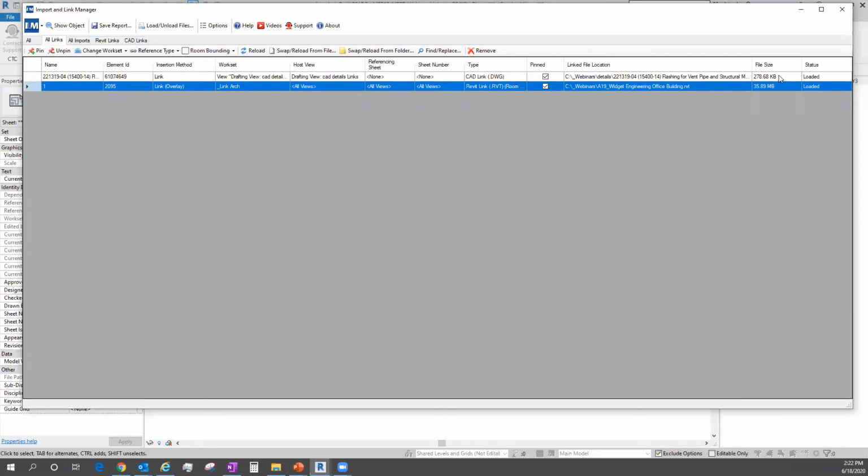So in those instances, if I see somebody's CAD file is absolutely huge, we'll probably take it back to CAD and try to simplify it. And if we can't simplify it in CAD very easily, you might even export that as an ACIS solid and then use that to turn it back into a family and then put connectors on it if it was required inside the MEP side, or if it was just a piece of equipment like a steel or cabinetry or whatever that might be. It may be a giant assembly of some sort that somebody's created, maybe in Inventor or SolidWorks, those types of things, and giving it to you as a CAD format. So a lot of times we can simplify those out. And if you know how to do that, that's a fantastic way to make that Revit file run much faster.